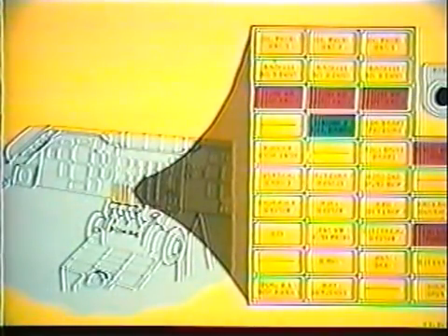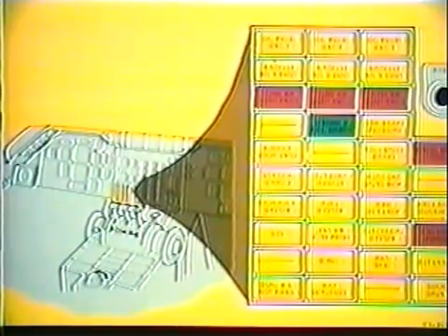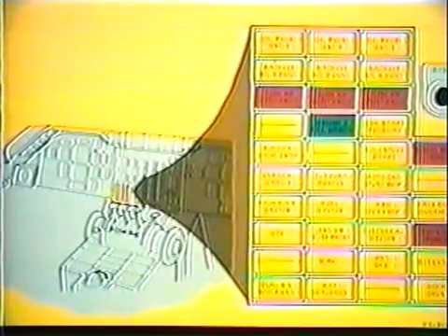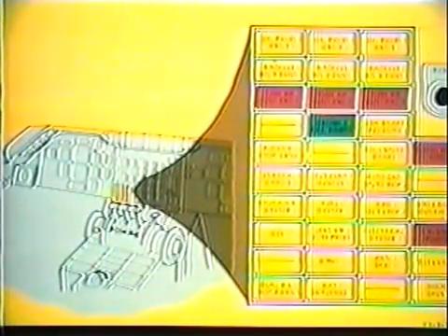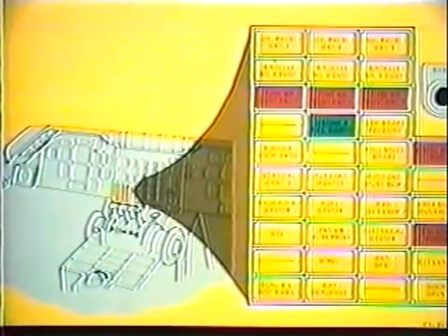When a malfunction occurs that is outside the normal vision of the pilot, a light on the pilot's annunciator panel will flash for 10 seconds, then remain on steady until the fault is corrected. The light from a fault not corrected can be extinguished by pressing the reset button.